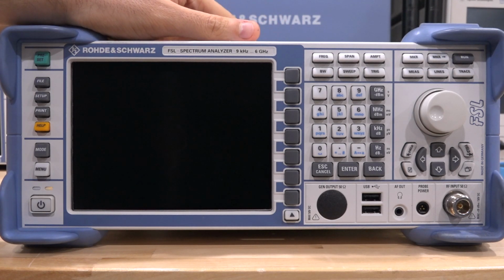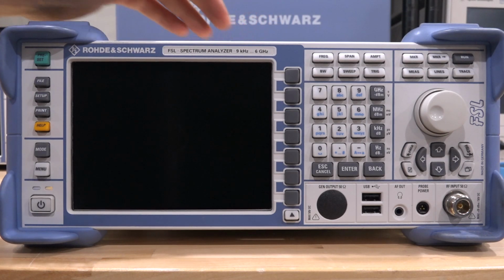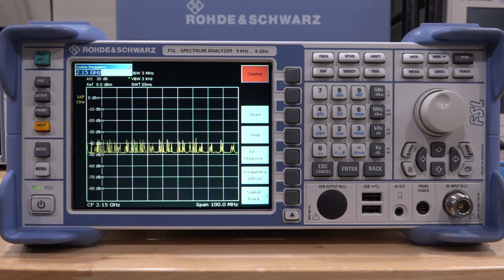And yes, I know it's not the front panel connector. It's definitely something much more serious. So let's turn it on and see what it does. And here we go, 2 minutes later or so, and we're in the firmware, and this does not look right at all. The noise floor of a spectrum analyzer is fairly white, especially within a small frequency span like the 100 megahertz we have over here.